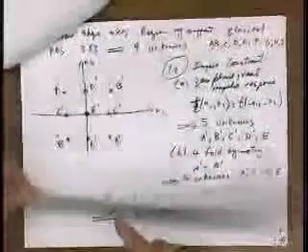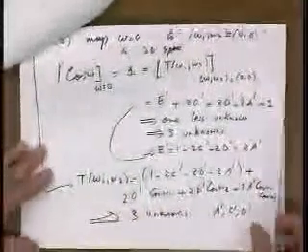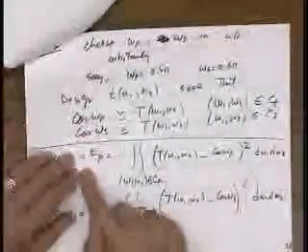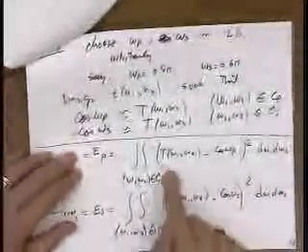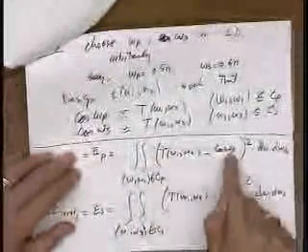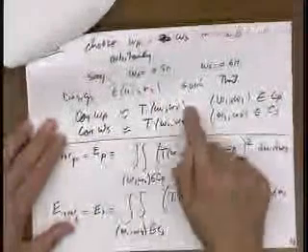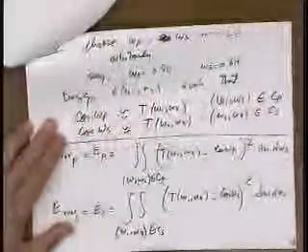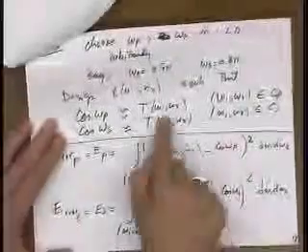Then we imposed a bunch of constraints. This was our T filter. We imposed a bunch of constraints, and at the end we came up with 3 unknowns, A prime, C prime, D prime. And then we came up with this error criterion, which says along the passband contour C sub p, we want the error between cosine omega p and T to be small, because for all values of omega 1 and omega 2 in the passband contour, we want these two quantities to be almost equal to each other. So we minimize this error, and the same thing for the stop band.